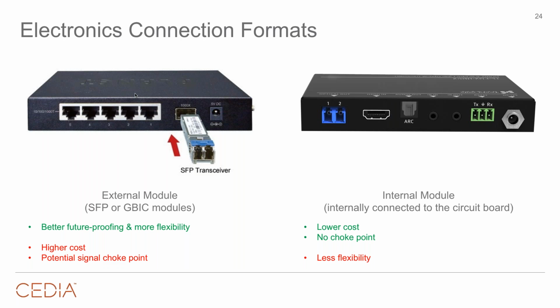Now, an internally designed product where there is no module in line doesn't have this issue. Now, we don't have the flexibility of being able to adapt from one infrastructure to the next. Usually, we are set at 1,000 feet, right? That's how most of these products are engineered. You got 1,000-foot distance, whether you use single mode or you use multi-mode, doesn't matter.